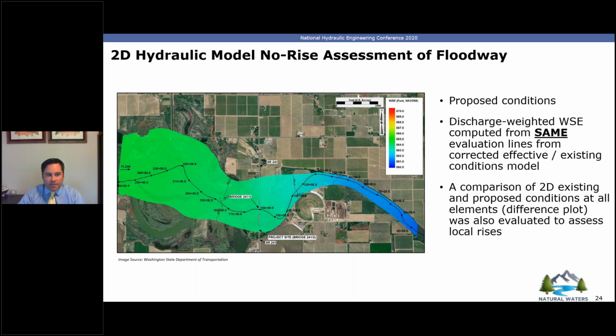So I guess my answer to that would be it really depends on what you're utilizing those velocity results for. And that almost is a separate presentation in itself, because if you're utilizing velocity results for doing contraction scour, you may want to use a similar type of discharge weighted value or cross-sectional average value in some of the scour computations.